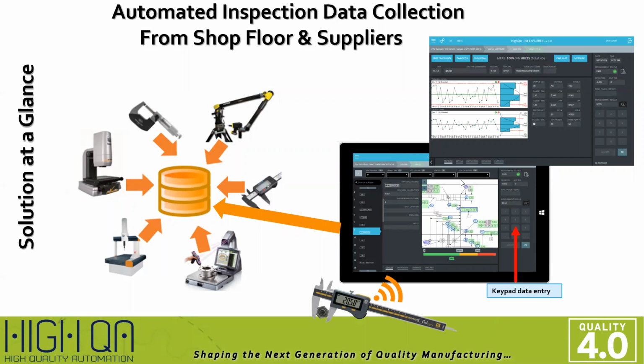And when we talk about real-time data collection, when we talk about SPC that gives you real-time, this is a simulated screenshot that probably Chris will show us later. When someone on the shop floor collects data and there is a control limit, it's real time. You can see exactly what happened when he collects data. And if there is something that's going to take it to a risk level, going close to the control limit, the system will alert him and other relevant people because all of them are on the same system.